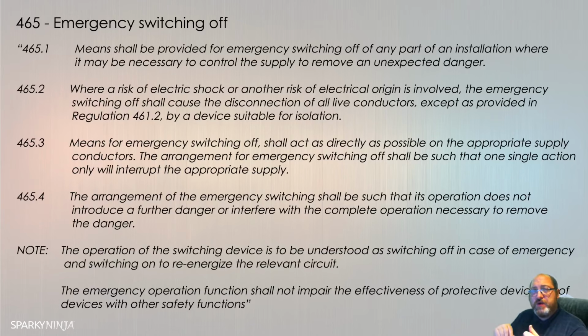Fault protection was earthing and bonding and protective devices, or in some cases isolating transformers or supplementary insulation. And there were 4 general protective measures. You had automatic disconnection of supply, ADS, which we've seen repeated a few times now. We had class 2 double insulation, we had electrical separation, we had SELV and PELV. The 4 general protective measures, and every general protective measure will achieve basic and fault protection.